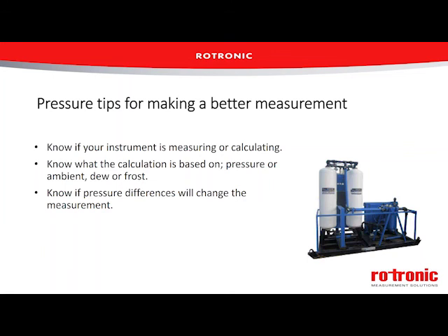For example, I've seen this happen too, where people take a sample off their compressed air line, they measure the dew point at the ambient pressure, and it looks great because remember, lower pressure, you get a lower dew point. So it looks great, and they think their system is nice and dry, but they didn't make the calculation, and it may not be as good, and it may not be sufficient to prevent water. So those are some tips for pressure with your day-to-day measurements of humidity parameters.